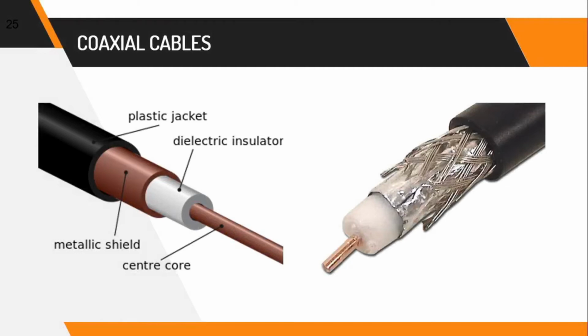The center conductor layer is a thin conducting wire, either solid or braided copper. A dielectric layer made up of an insulating material with very well-defined electrical characteristics surrounds the wire. A shield layer surrounds the dielectric layer with metal foil or braided copper mesh. The whole assembly is wrapped in an insulating jacket. The outer metal shield layer of the coaxial cable is typically grounded in the connectors at both ends to shield the signals and as a place for stray interference signals to dissipate.